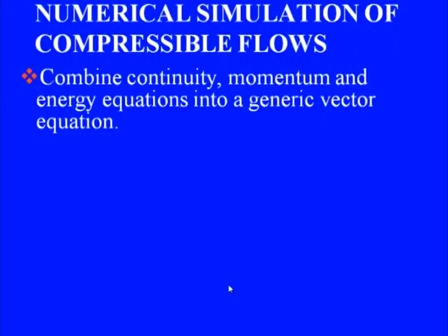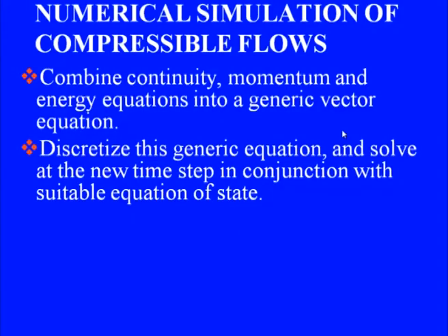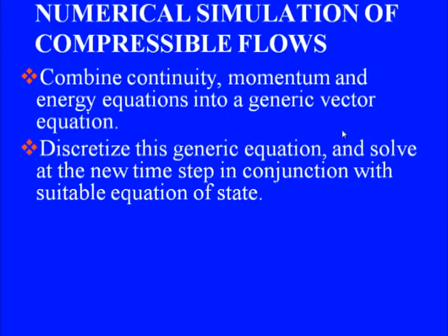We will just take a brief algorithmic look at the solution of compressible flows. We will combine continuity, momentum and energy equations into a generic vector equation, that is what is normally done, and then we will discretize this generic equation. Usually the simplest way would be to choose an appropriate explicit time integration scheme and obtain the solution at the next time step in conjunction with a suitable equation of state to get our pressure.